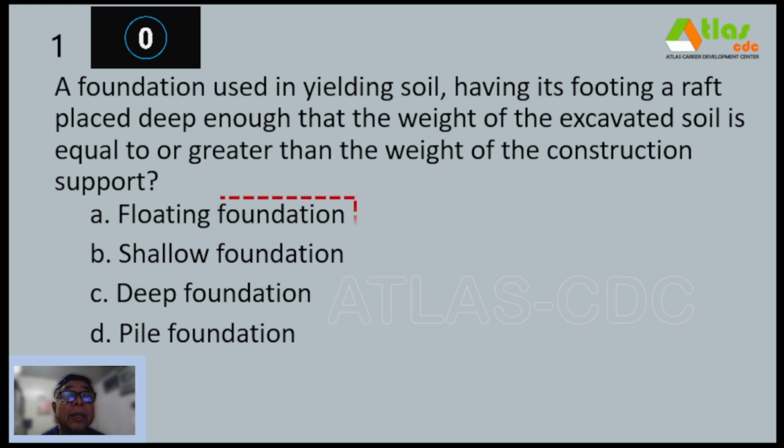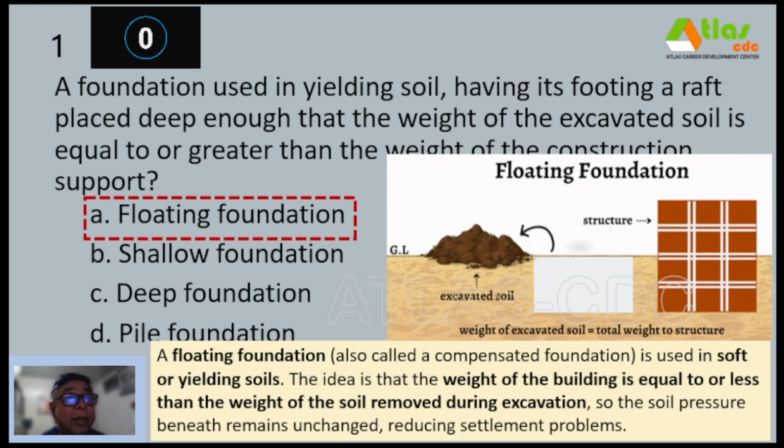And our correct answer is letter A, floating foundation. So a floating foundation, also called a compensated foundation, is used in soft or yielding soils. The idea is that the weight of the building is equal to or less than the weight of the soil removed during excavation. So the soil pressure beneath remains unchanged, reducing settlement problems.